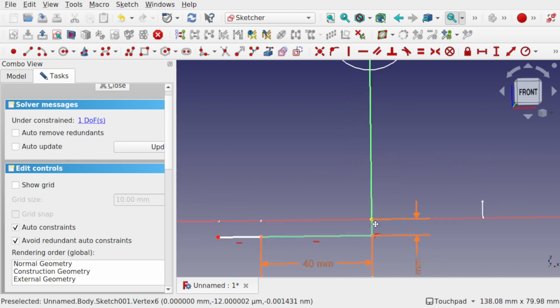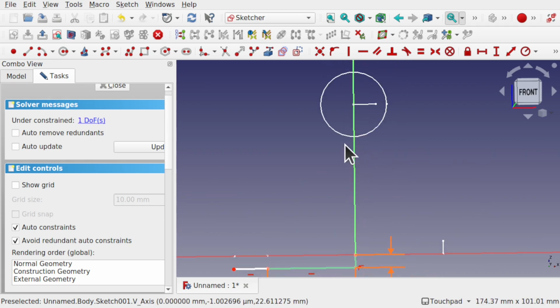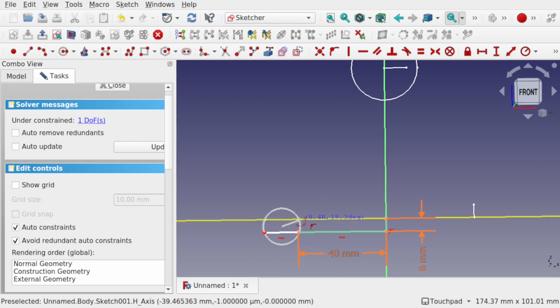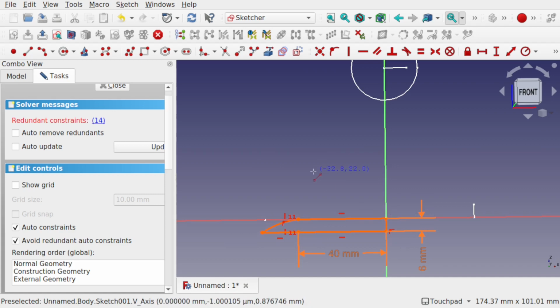So we've started creating our shape. Now we need an arc, so I'm going to pull in our arc. I'm going to use endpoint and rim point. Click on this one and come into about here on this line and just bring this arc around. I'm going to make sure, hit escape, make sure that these two points here are in line, and place another line to connect up with this one. It's a coincident constraint to that center point there, and delete any redundant constraints.